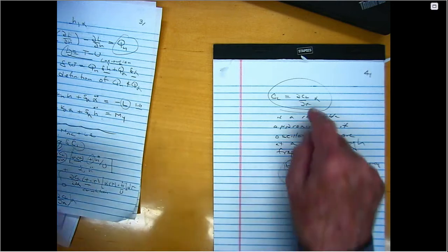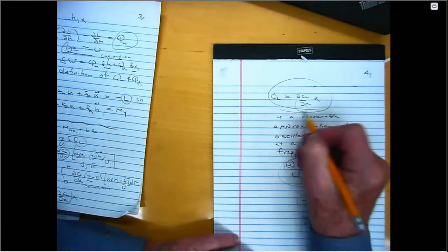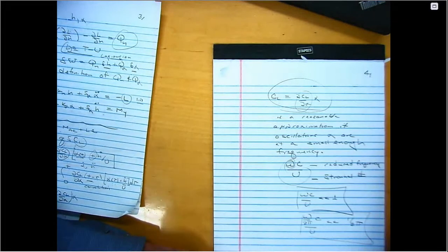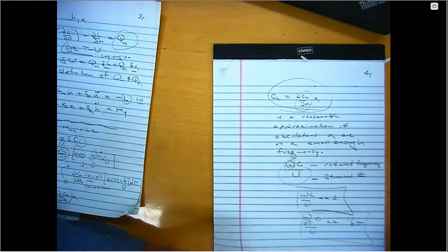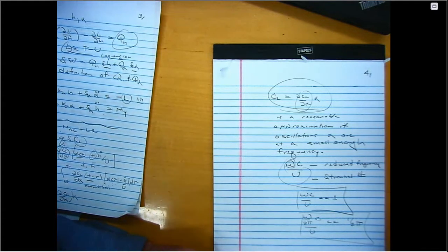Okay, so this is actually not a bad thing. Now, this thing still depends on Mach number, for example, right? At low speed, of course, it doesn't, but if I get near Mach 1, this thing changes with Mach number, yes. So this approximation that we have for the lift coefficient is valid for reduced frequency much less than 5. Right. And we're using this for a flutter analysis. However, it's not present of a flutter that typically occurs at higher reduced frequency. It could. Yeah, the reduced frequency will turn out to be whatever it is.